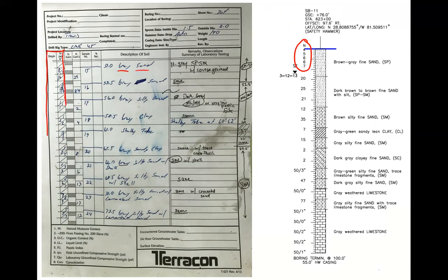Other things that they say, this says gray sand, gray silty sand. So this is the description of the soil sample at each depth. And then the depth is shown here. This is the second page. This is at a 51-foot depth. This was kind of south of Tallahassee. And then we'll have other information here where we have the drill rig type. So this is a CME 45, and we'll talk about the importance of the drill rig type in a second. And then other things like the outside diameter, the weight of the hammer, and the type of hammer used too.